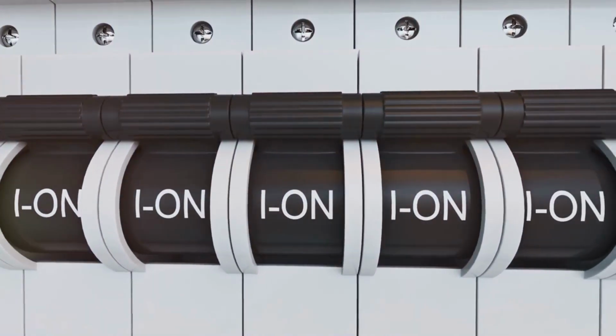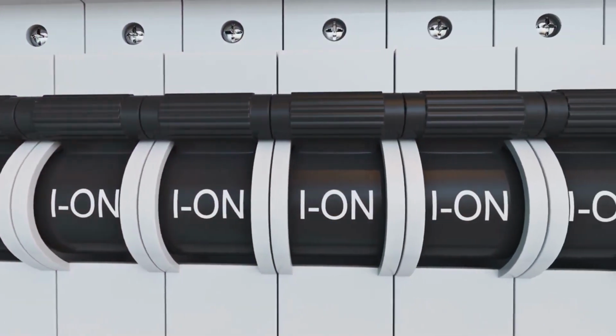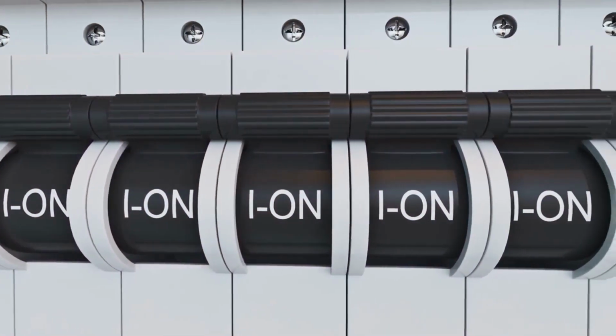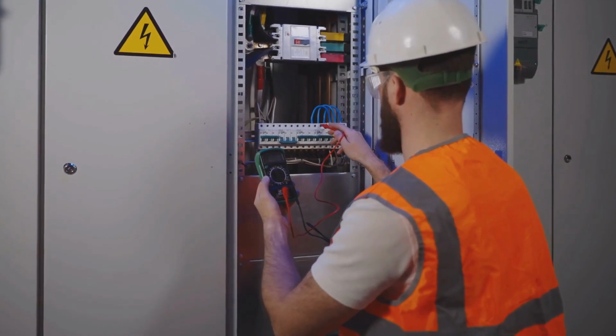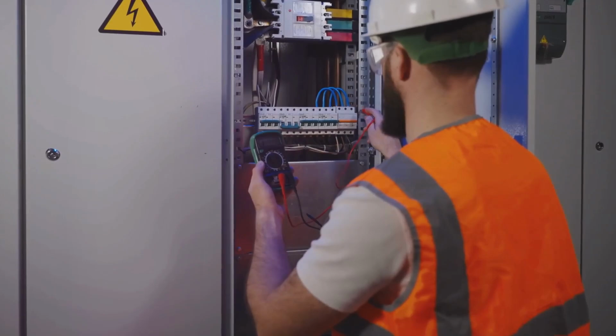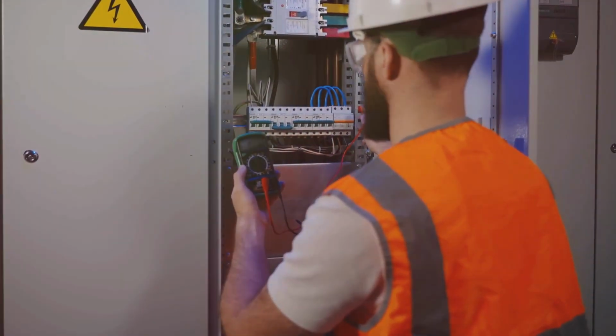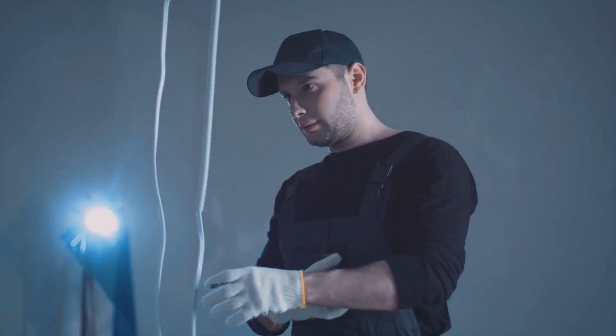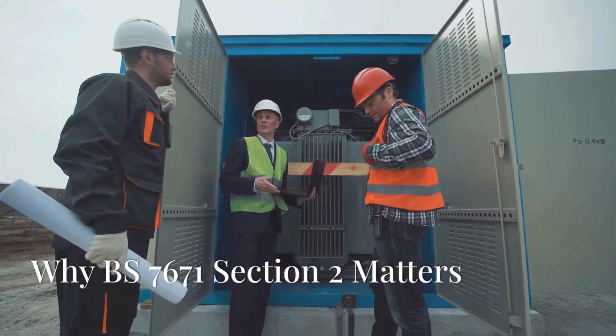Clear labeling. All isolation switches should be clearly labeled so that it's easy to see which equipment they isolate. These measures are crucial for the safety of electricians and anyone working on electrical equipment. Proper isolation procedures prevent electric shocks and ensure a safe working environment.